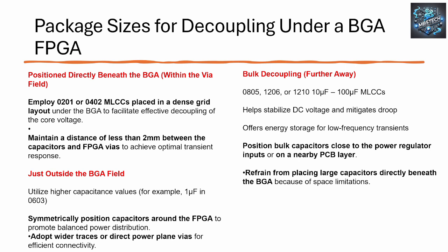It depends on your inspection techniques, whether you use a microscope or you just X-ray, as to how close you can get your capacitors to the BGA on the top layer, the same layer as the part itself. Most people these days X-ray things, so you can get it close, especially with IR reflow technologies and so forth. You can compact things quite a lot.